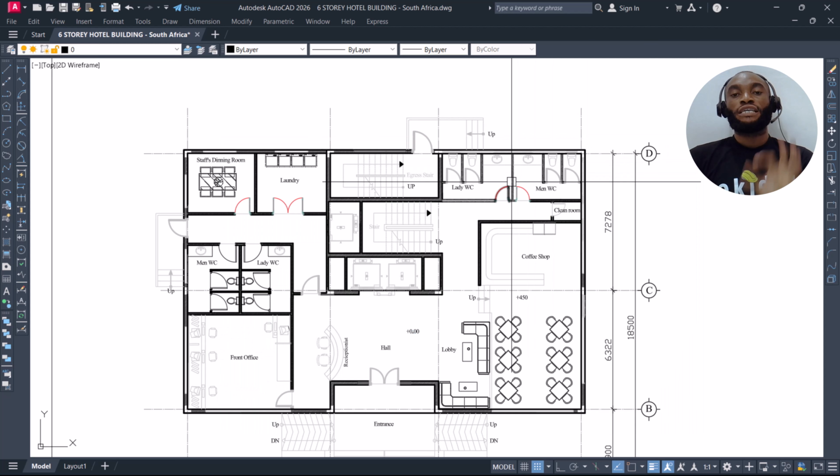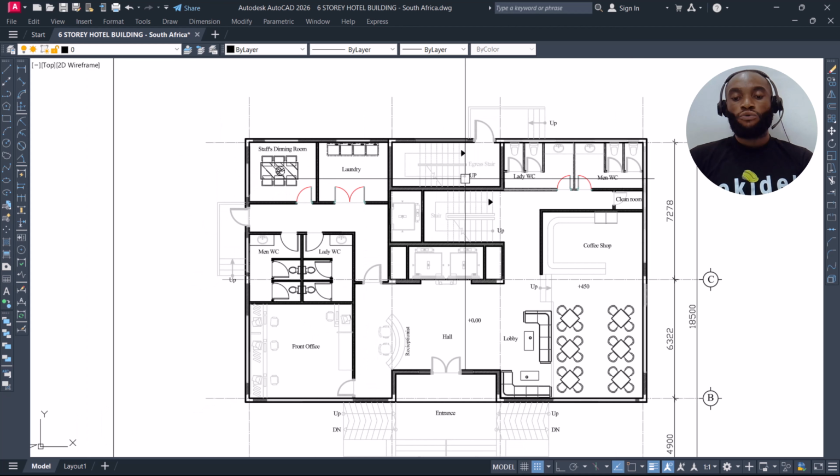So these are the only 2 layers the software requires you to use for your structural framing. Now you can also create beams and walls, which after you import it, you will see your beams appearing, but that's in a complex way, which I will show you guys later. But in this, I want you guys to focus first on using the grid layer and the column layer in performing your structural framing. So with this now, we will proceed.